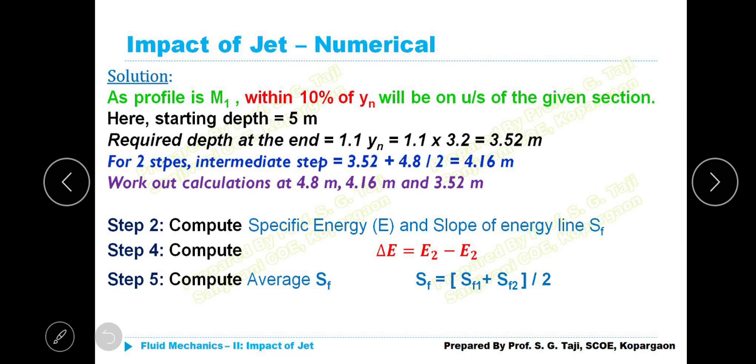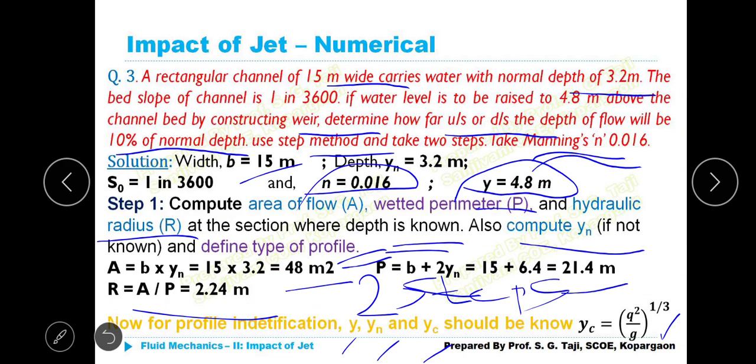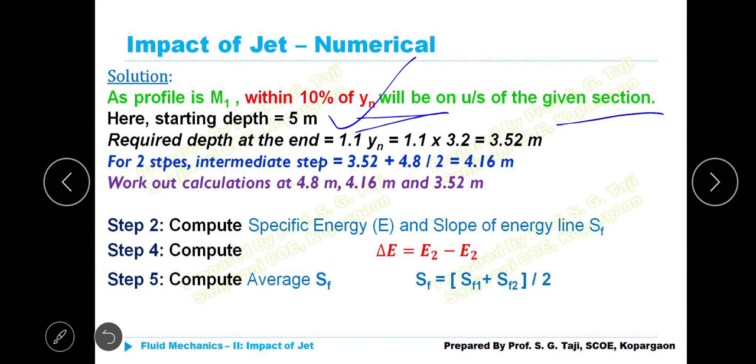Solution now. As the profile is M1, within 10% of Yn as per the given data will be on the upstream side of the given section. Here, the starting depth is 5 meter, because that is given as 5 meter. Initial starting depth is 5 meter.